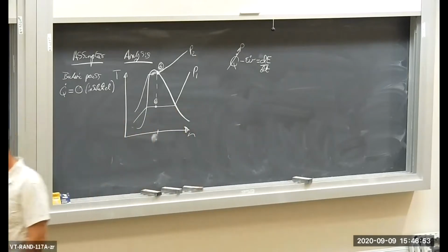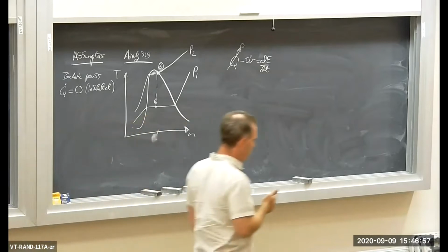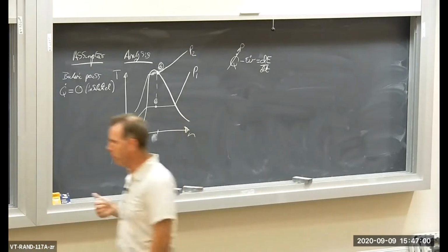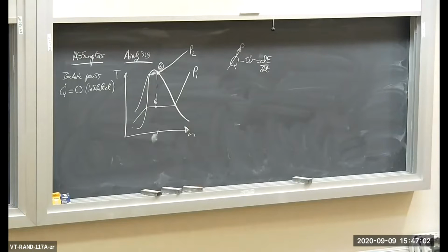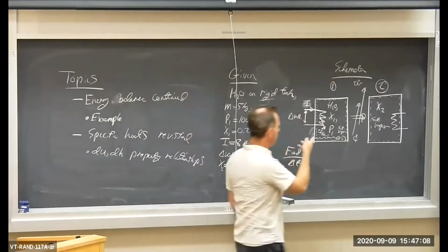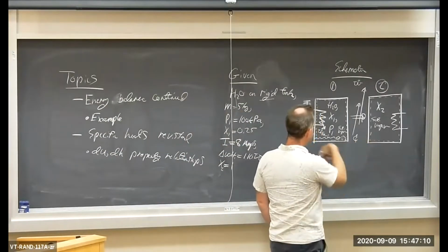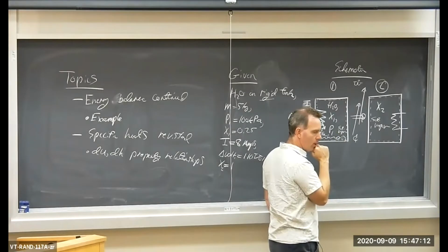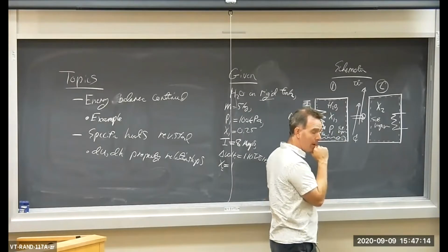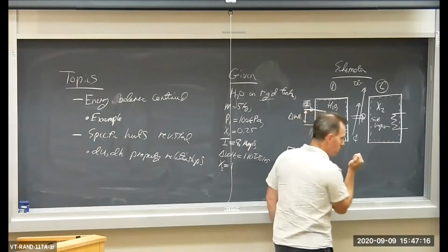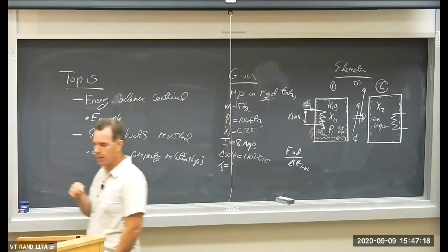What's the W dot term? Well, we know we have some electric work. No shafts, no propellers inside this tank, so there's no shaft work. It's a rigid container, so volume is constant. It's an isochoric process, so boundary work is 0. So electric work is equal to the work.